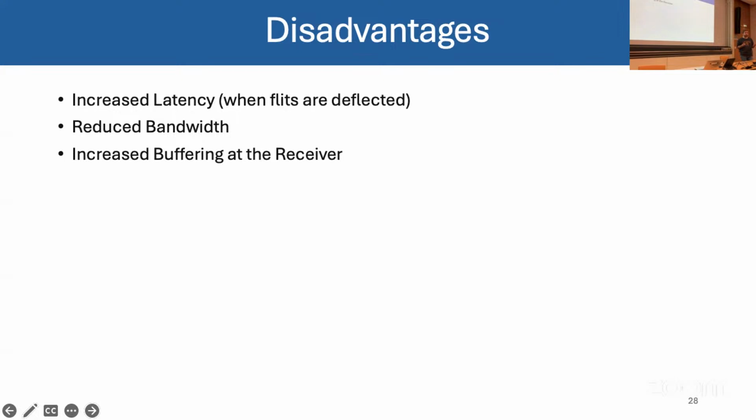As I said, when the flits arrive at the receiver out of order, or not close in time, then the buffer might have to be quite large. Additionally, we have this header transmission with every flit in FLIT-BLAST, and even in WORM-BLAST we have this huge overhead that we're paying for the header, even if the body flits don't contain this information anymore.